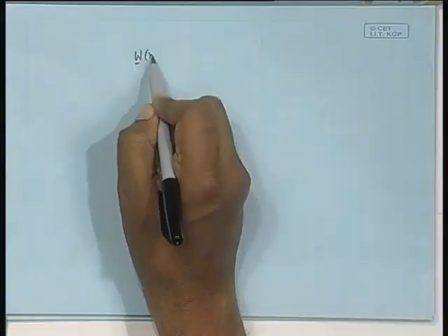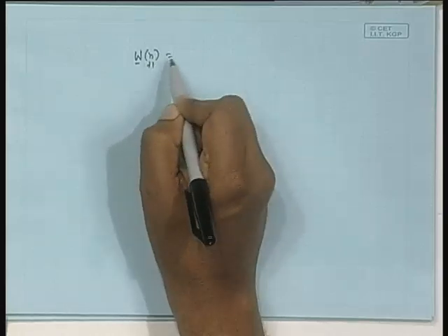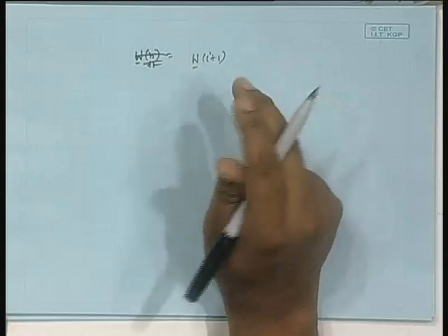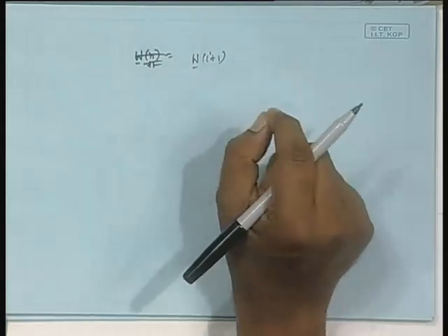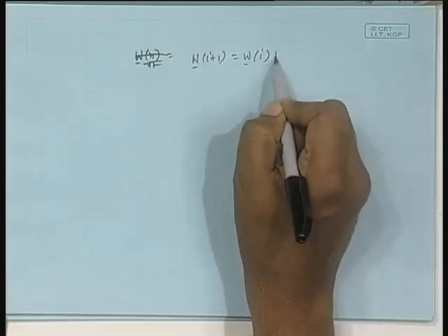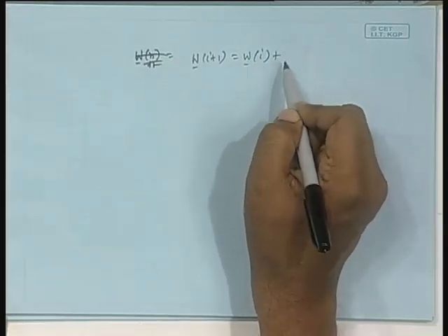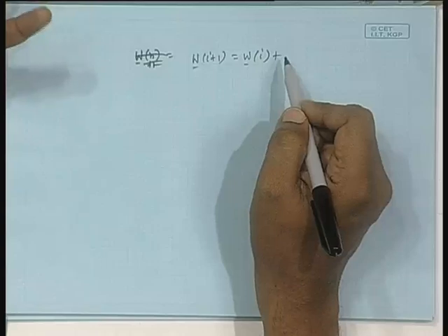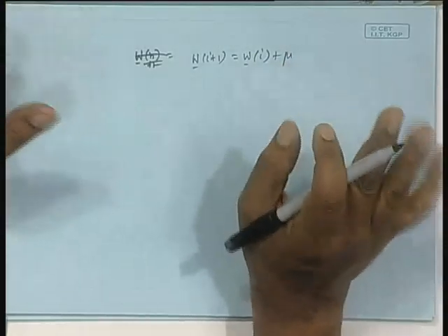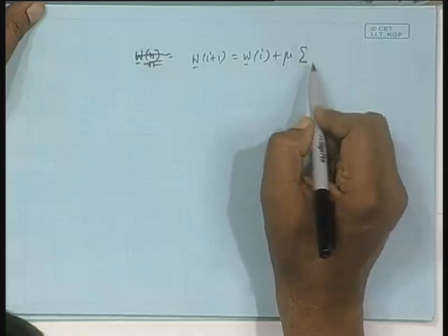Now, the weight update part. In the weight update part, you can see one thing. Let me write down elaborately W(i+1), not n, because it is block LMS. There is no question of updating with time n, we are updating with block index i, plus mu by L, call it mu, because any constant will do, it is the computation I am bothered about.